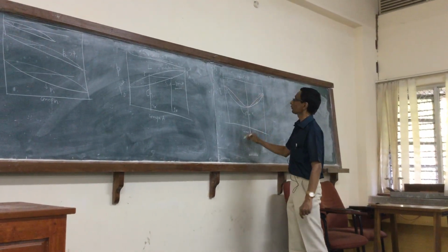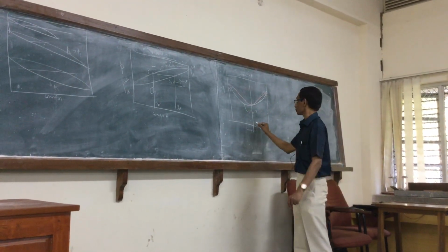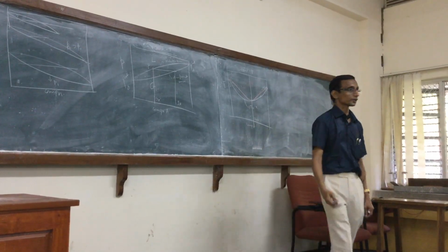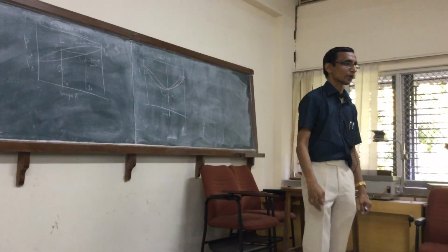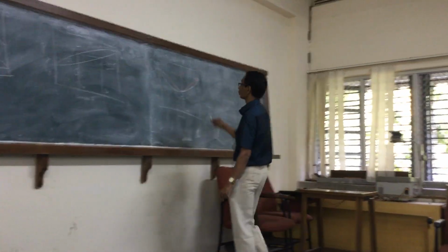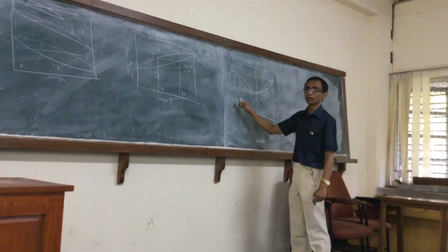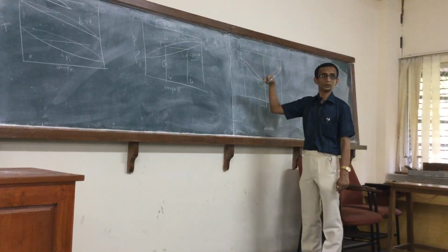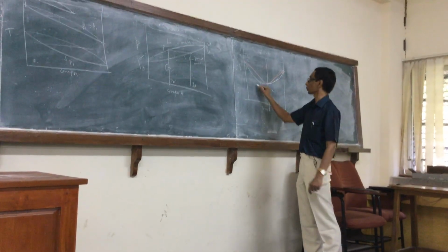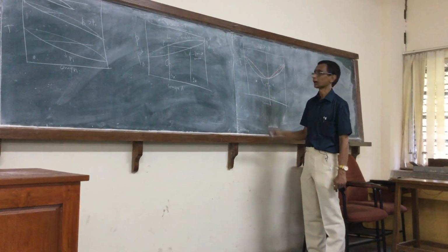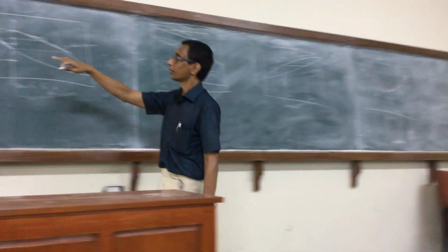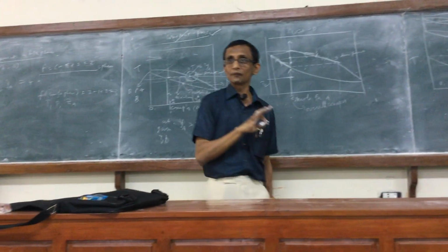At the azeotrope, you see what happens. Now let's look at the composition, let's call this Z azeotrope. That's the composition corresponding to the azeotrope. Why it is called an azeotrope, I don't know. But now you look at compositions to the left of the azeotrope, that means compositions lower than that of the azeotrope. I take a liquid here, and heat it. Whatever your experience there, exactly the same thing will happen.